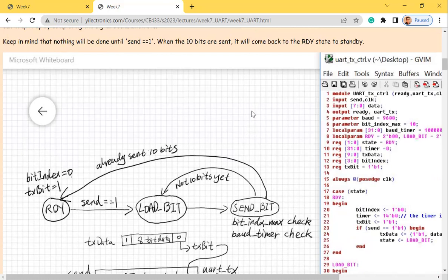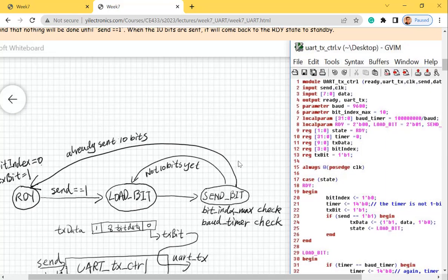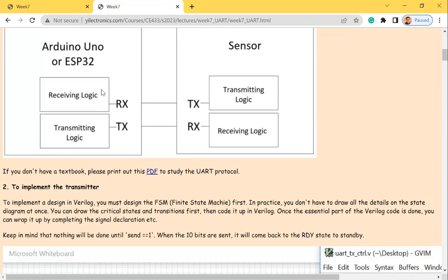So which means if we design or implement the TX logic module in our FPGA, for example, and we connect it to RX of the Arduino board, even though we don't know who wrote that RX logic for the Arduino chip, they are going to communicate. That's why we are trying to standardize all these communication protocols, since we know they have the same protocol. If I pull it down, the receiver is going to know that I'm trying to send the 1 byte data right after that logic 0.